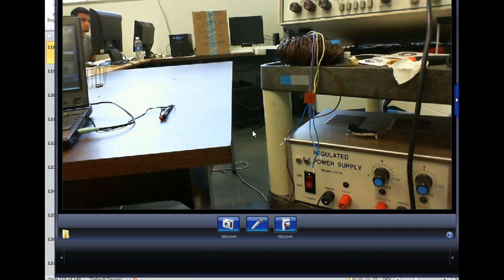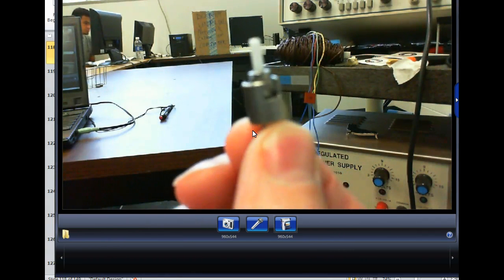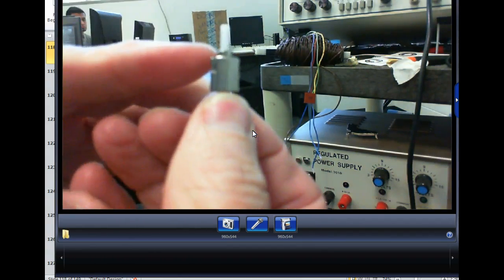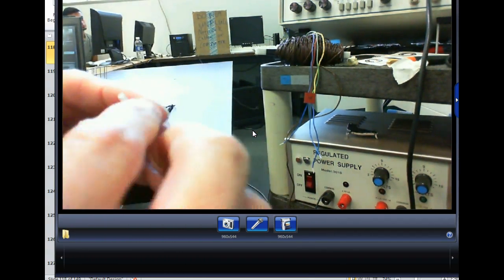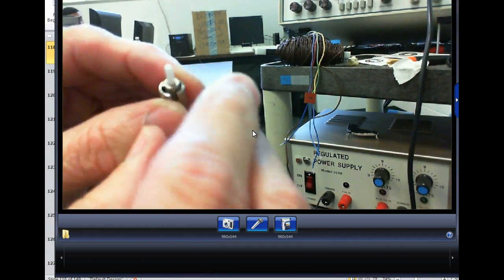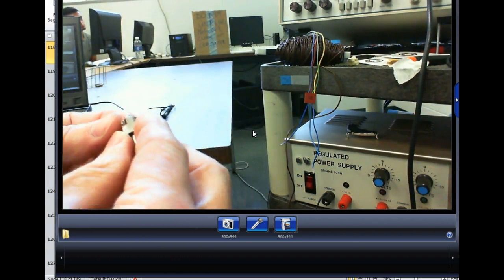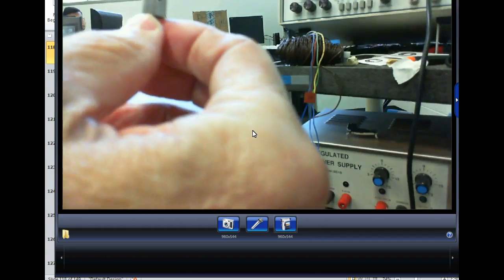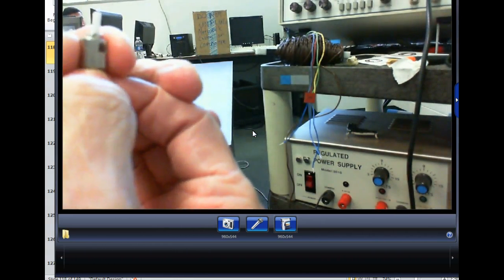Some are plastic or ceramic. Everybody know what the ferrule is? We need to keep it really clean. It's got a tiny hole you can't even see on the end, which is where the fiber is going to come out, and this is sized for 125 micron cladding.